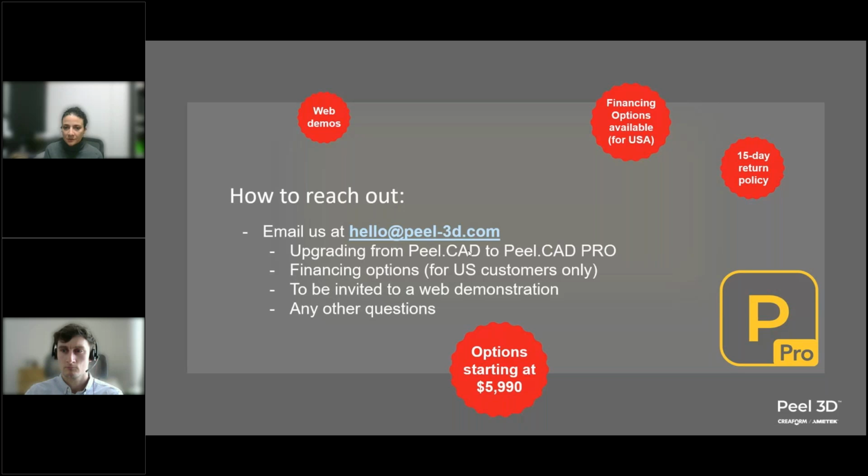But with the inspection software, that goes one step further, where you can actually do GD&T callouts, like parallel, and then you can do like perpendicularity. You can tell the software what your tolerance requirements are. So if you have a diameter that's plus or minus 0.5 millimeters, you would state that that's the value, and then the software would tell you whether those dimensions pass or fail. And then at the end, you can create a report that allows you to show exactly what your part is doing according to your dimensions that you might have from your 2D drawing, for example.